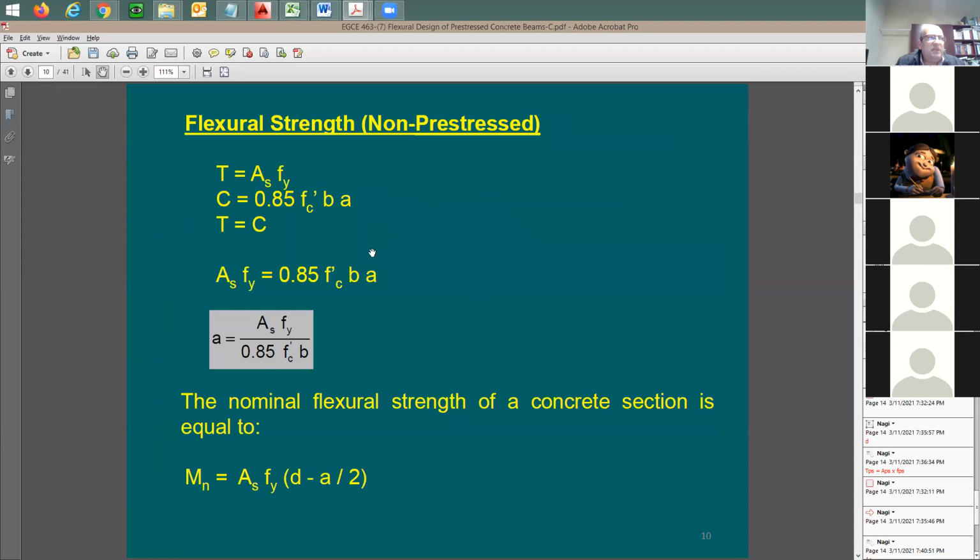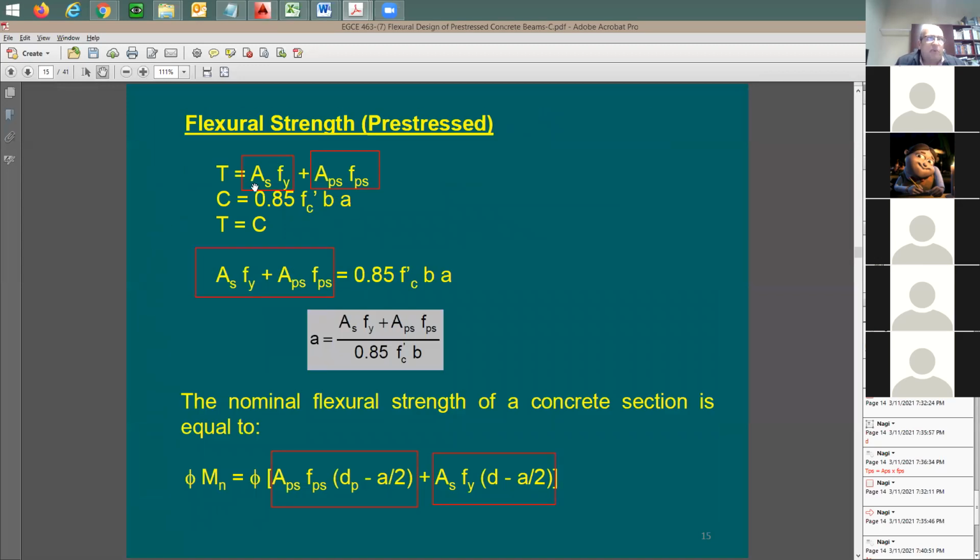This one here, I just have the conventional rebars, like number 6s and number 5. So I can play with this. At one time, I can have both of them, or I can just eliminate any one of them and solve exactly with the same equation. So this is a more general equation for the flexure strength. And at one time, you can take this out or keep it. It depends on what reinforcement that you're planning to put in your beam. So we use it basically to prevent cracking.